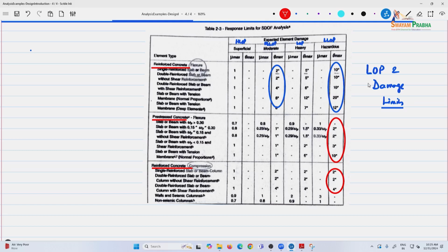Mostly RC damages you can't really predict, and in the columns there is a lot of stiffness in the material, right? Because of the loss of damage, spalling, we talked about breaching, all those things. So as soon as those two effects start coming in, the stiffness drops considerably and the column still has integrity, but it deforms a lot. Whereas pre-stressed concrete is designed for elastic behavior.